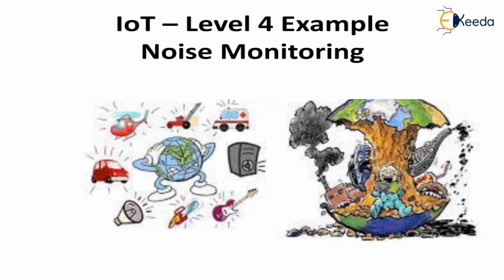The noise monitoring systems can be installed outdoors on a street light or directly on a wall. It includes a damp-proof microphone and a protective cover to shield it from the elements. Communication modules like 3G, 4G, and LoRa long-range communications are used. Next, data display and analysis, which is integrated with the wireless communication modules.